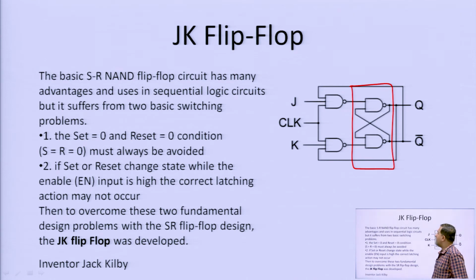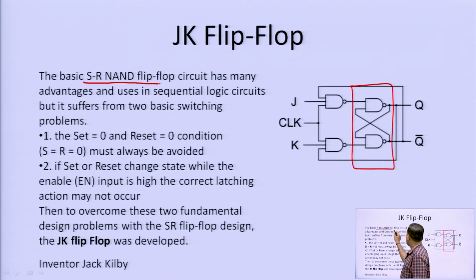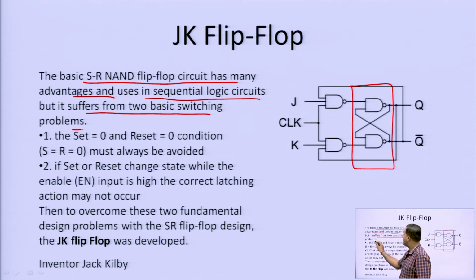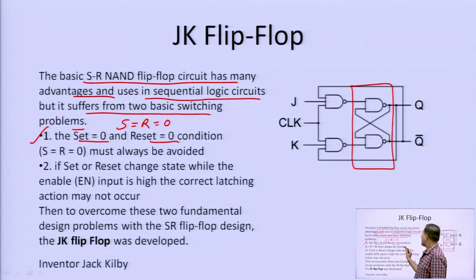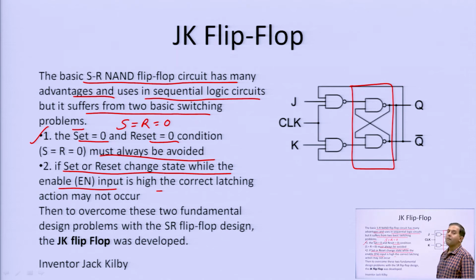I can tell in brief that the basic SR NAND flip flop circuit has many advantages and uses in sequential logic circuits, but suffers from two basic switching problems. First, if set is 0 and reset is 0, means if S and R both are 0, then it should be avoided. And if set or reset change state while the enable input is high, the correct latching action may not occur.